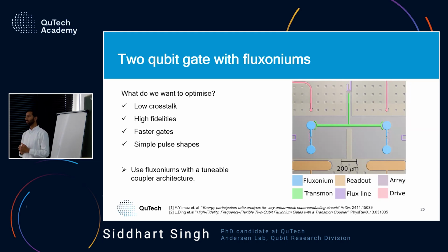On a chip, approximately how many devices? So we used to put 4 sets of these on each chip, and sometimes not all the sets are working on the same chip, so you would get 1 or 2 working sets, and within those sets sometimes the coupler is exactly close to the resonator, so your leakage is high. And I think it took us 6 of those chips before we could come close to the exact numbers.